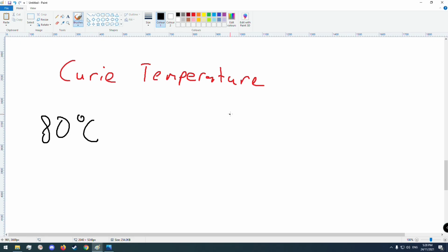Ferrite magnets, on the other hand, can be upwards of 350 degrees Celsius, which is well out of the temperature range of the voice coil. They're never going to get that hot. So as a standard ferrite, say subwoofer, gets hotter and hotter, its magnetic performance should stay quite flat.